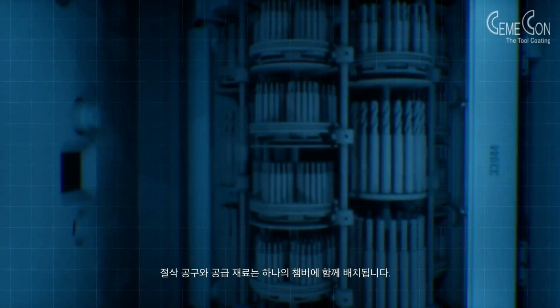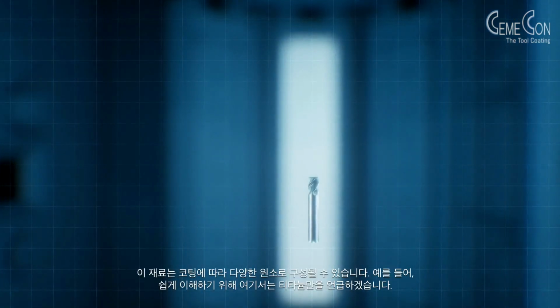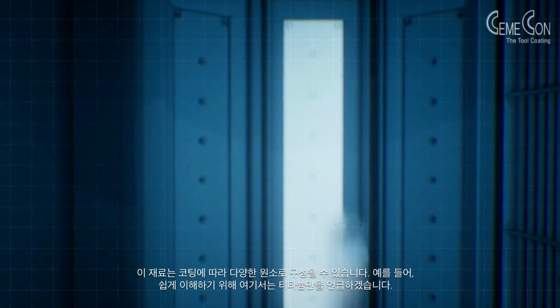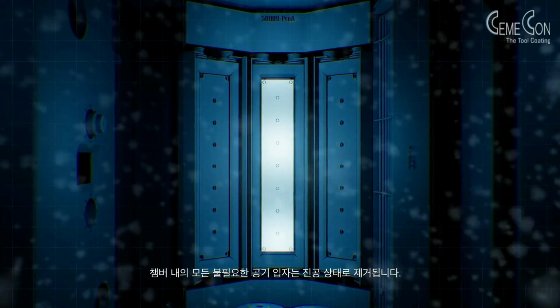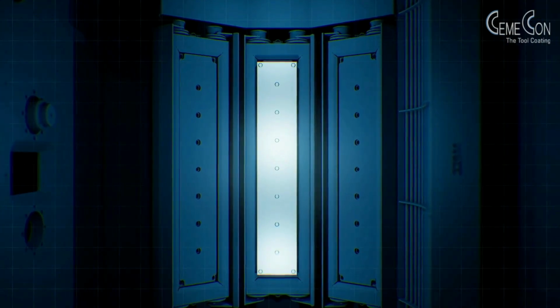The cutting tool and the donor material are placed together in one chamber. This material can consist of different elements depending on the coating. In our example, and for the sake of simplicity, we'll speak only of titanium. All unwanted air particles are removed from the chamber by a vacuum.